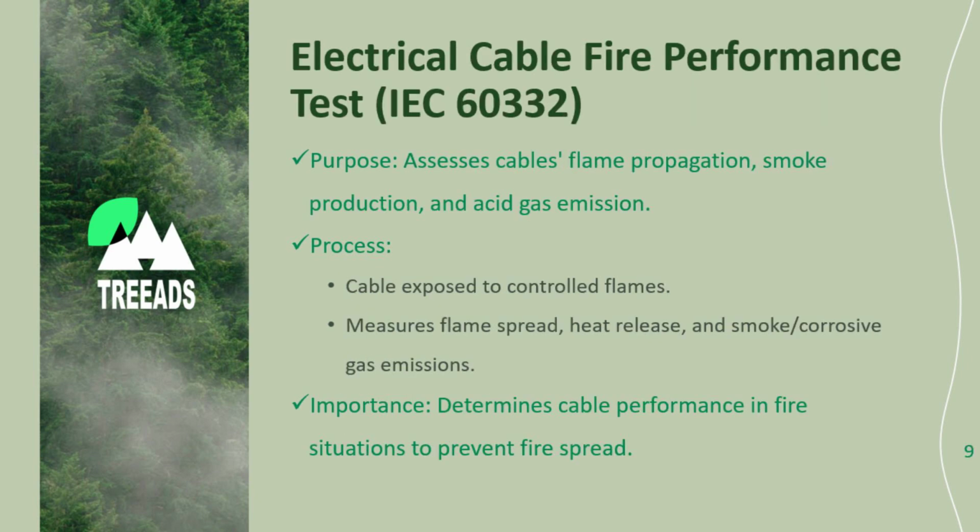The electrical cable fire performance test is used to assess the flame propagation, smoke production, and acid gas emission of cables subjected to fire. This test involves subjecting the cable to a controlled flame and measuring various parameters such as flame spread, heat release, smoke density, and release of corrosive gases. It helps determine the performance of cables during fire incidents and their impact on the spread of fire and survivability.